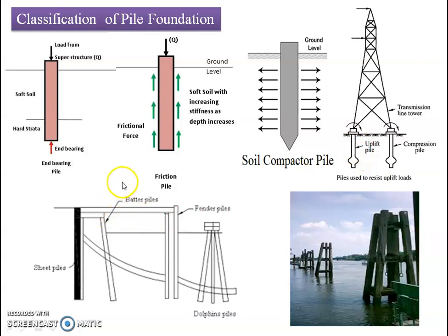In case of river bank stability, or alluvial soil, or very loose soil, we are going to erect a retaining wall made with sheets. Okay, these sheets are very thin members. They are going to be inserted in the ground with a cantilever action, the same as a retaining wall. On one side they will retain the material which is loose, and on the other side they will provide protection. For example, if I am going to create it near a river bank, on one side there will be water and on the other side there will be backfill.